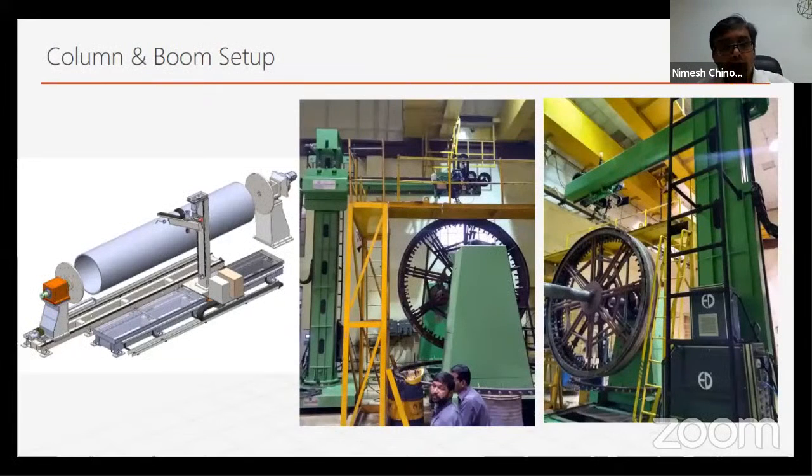Now, if you had a larger job, big vessels, pressure vessels, and the likes of that, this is used for aviation. This is a part of the Chandrayaan-2 solid fuel carrier. You can see this is a 3.2 meter shell. They've used spiders to make sure that the job is absolutely centered and not oval.